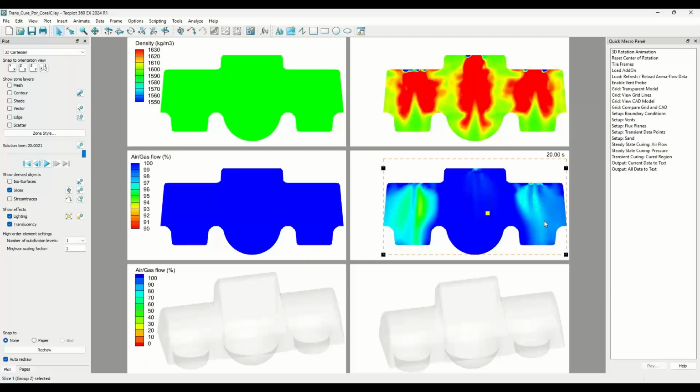I see. So the bottom is your overall view that we typically see, is it cured or not? That scale looks like it's from 90 to 100%. Would that mean more, perhaps, trapped amine? I mean, you wouldn't want it on SO2, but perhaps not purged well? Yeah, you can see it's just going to be a little harder to purge out the last amine in the two sides of the core, the right and left.